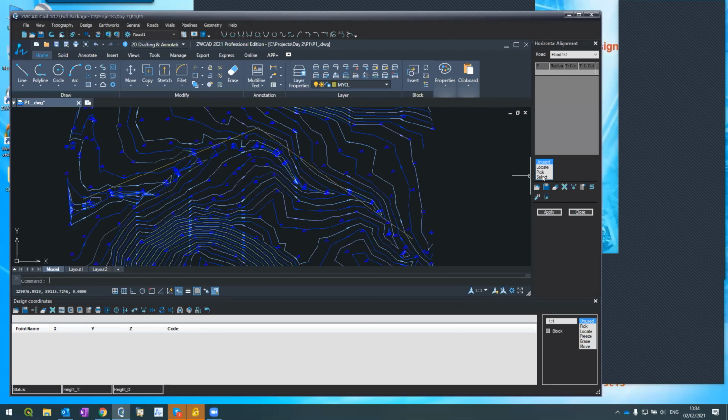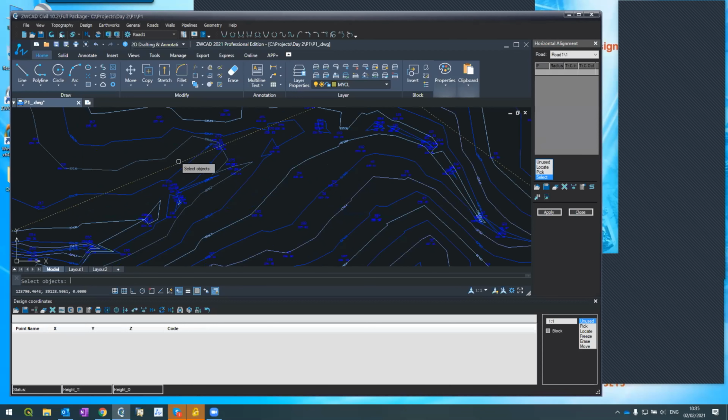I'm pressing select on this list on the right window. See what's happened in the command line of the ACAD. It says here, I'm reading from the command line: Enter an option, polyline, which is default, or segments. I'll press enter for the default polyline because this is what I created. Then it says select the object. I select this object. Then I press enter.